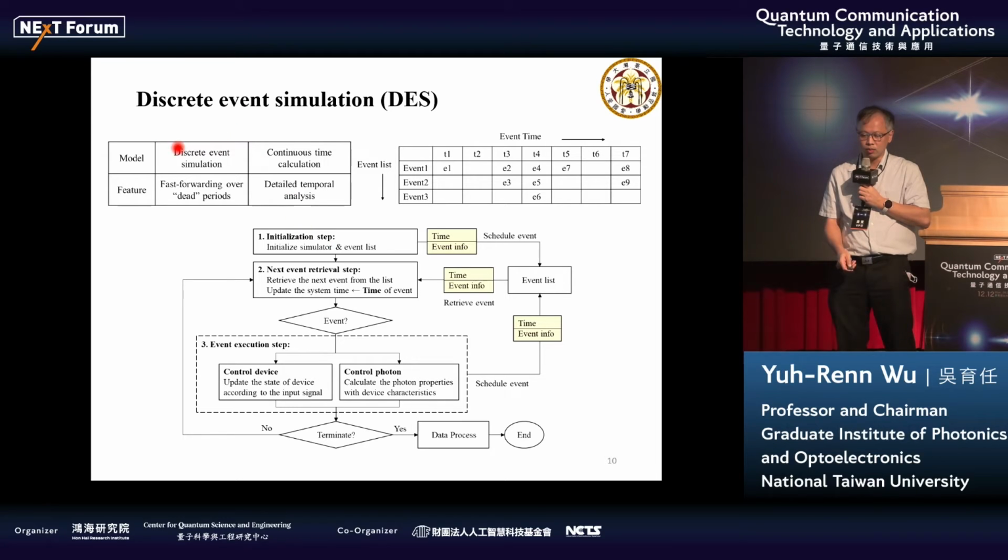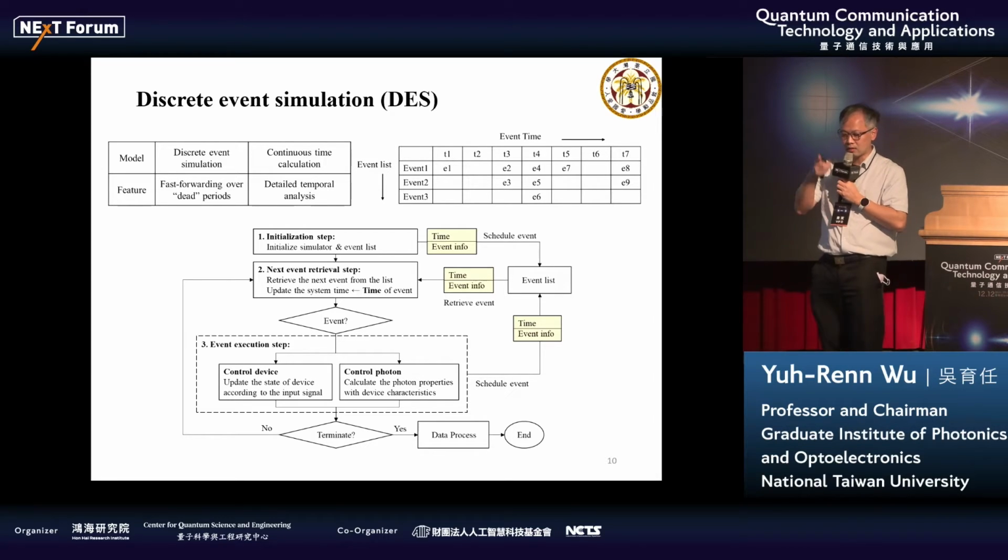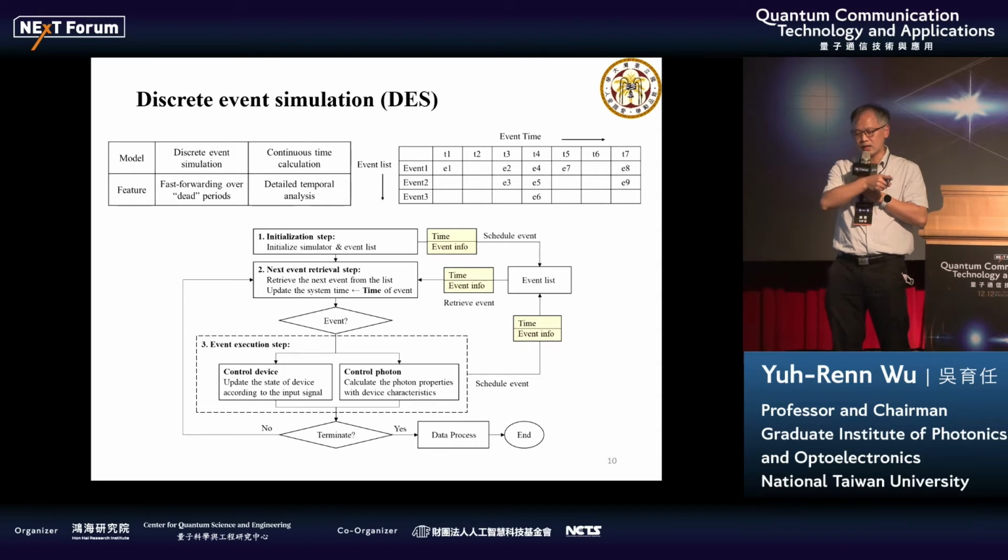All right, the difference from the optical simulator is that we use discrete event simulation. So we use a single photon as a source, then we simulate how the photon goes out from the source and into the waveguide, how much loss, then into the fiber, how much loss you get, and then into the interferometers, whether you go up or down, then you get to the detector, and the detector decides which detector will detect. If it's not reached, you will register. If it's refracted, you go to the loop again, and it continues until the end of the photon, and you get a signal. So it fully simulates the transfer process through the whole device.